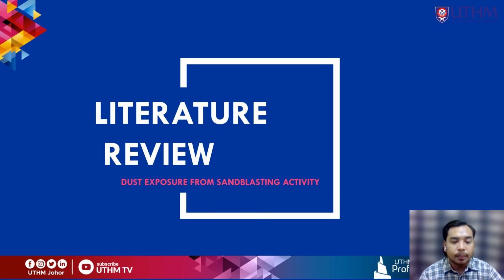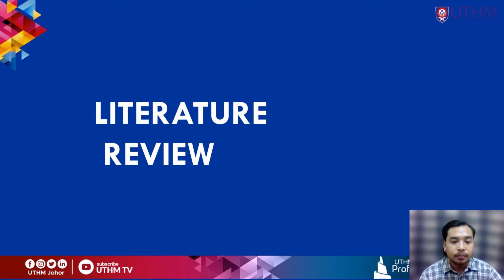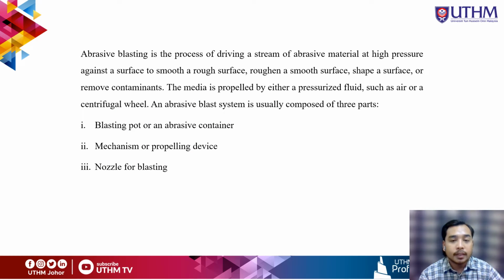And the second topic is literature review. Abrasive blasting is the process of driving a stream of abrasive material at high pressure against a surface to smooth a rough surface, roughen a smooth surface, shape a surface, or remove contaminants. The media is propelled by either a pressurized fluid such as air or a centrifugal wheel. An abrasive blast system is usually composed of three parts, which are the blasting pot or an abrasive container, a mechanism or propelling device, and lastly a nozzle for blasting.